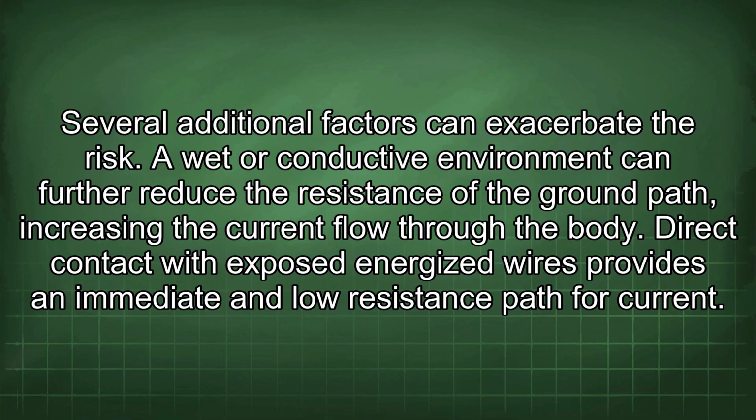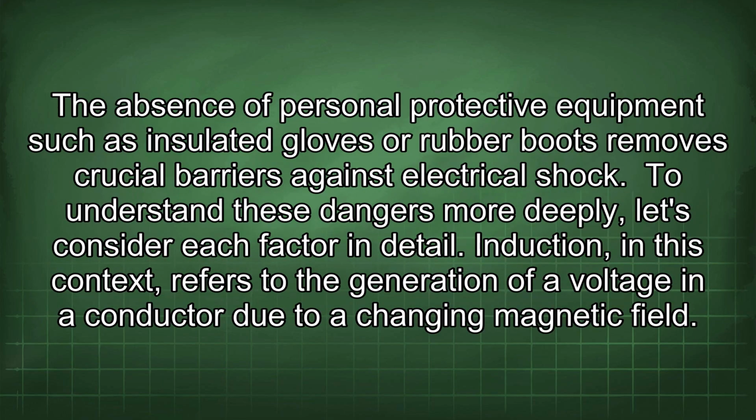Several additional factors can exacerbate the risk. A wet or conductive environment can further reduce the resistance of the ground path, increasing the current flow through the body. Direct contact with exposed energized wires provides an immediate and low resistance path for current. The absence of personal protective equipment such as insulated gloves or rubber boots removes crucial barriers against electrical shock. To understand these dangers more deeply, let's consider each factor in detail.